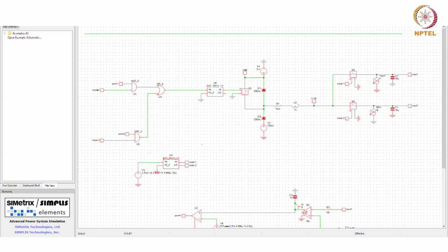So won't the other switch go completely unregulated for one cycle? It won't go unregulated. Your duty cycle will modify accordingly actually. That's why I said when you are in CCM, this SIDO or SIMO operation is not easy. When I say cross regulation, that's what it means. Cross regulation means one output tries to disturb the other output and it will never regulate actually. It will go out of regulation.